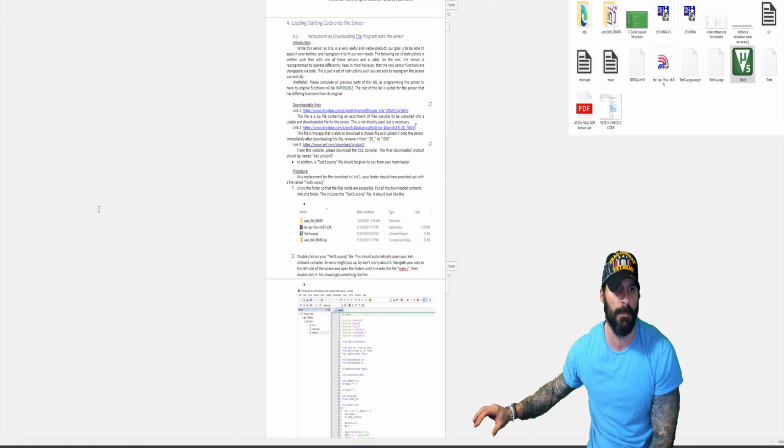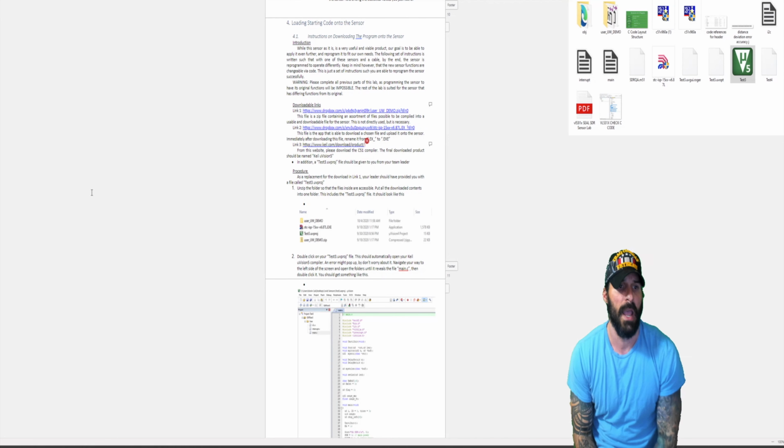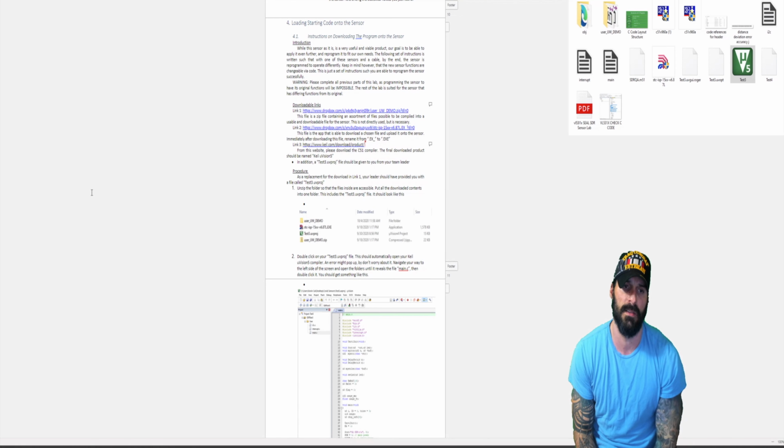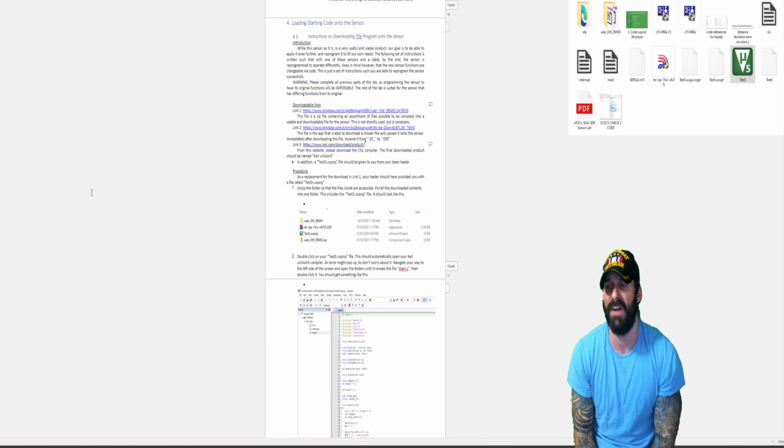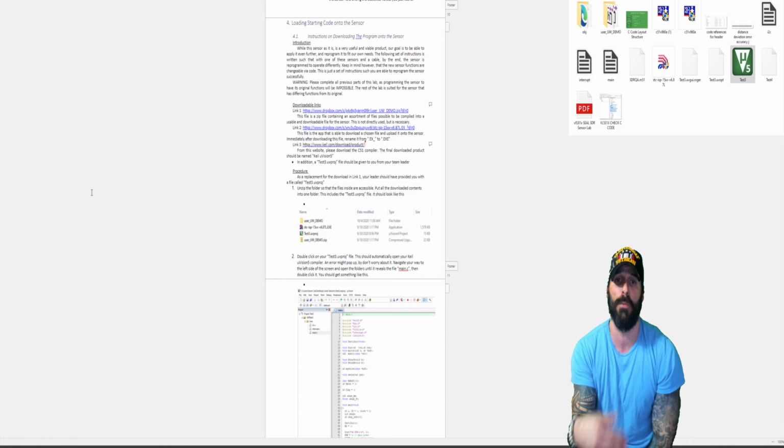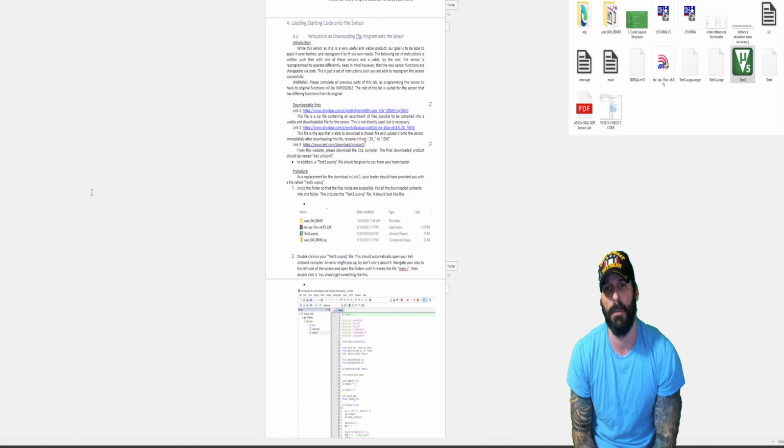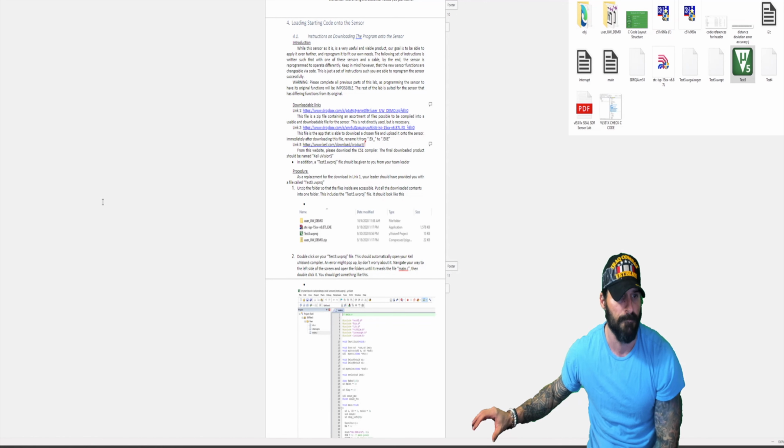And then on step number 3, we're going to have this right here, and this is the C51 Keil compiler. This is mandatory. You need this. This is going to upload that project file number 3 that we submitted to you, and then you can modify this in project 4, project 5, project 6 as you continue to modify for your final project, okay?